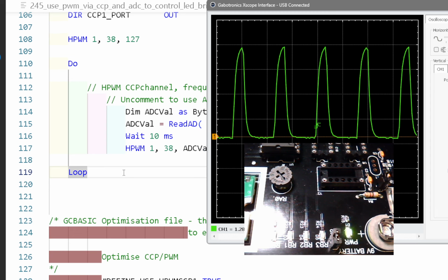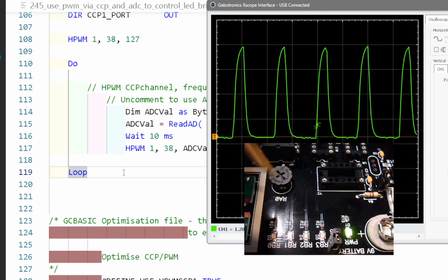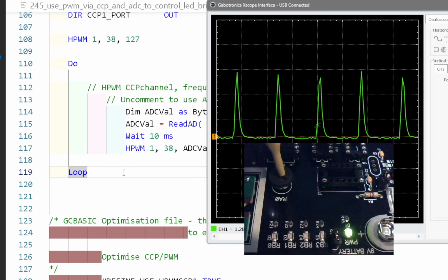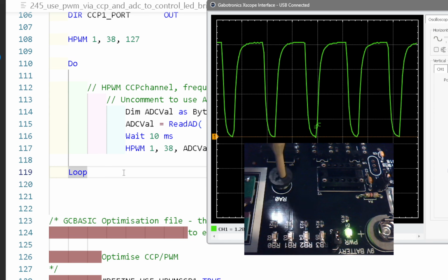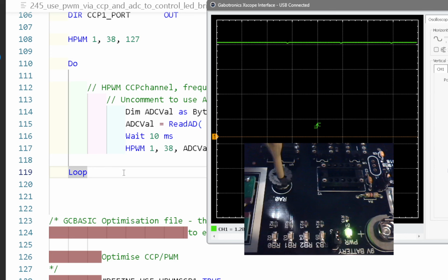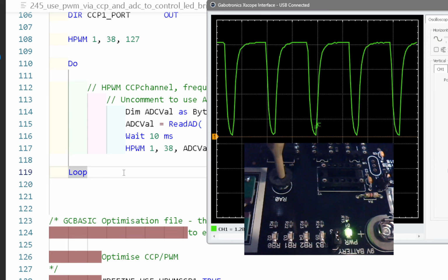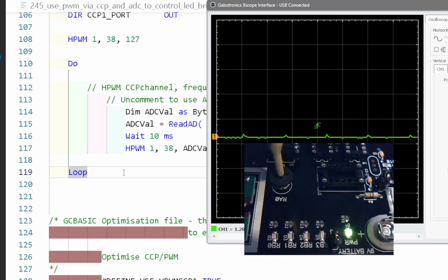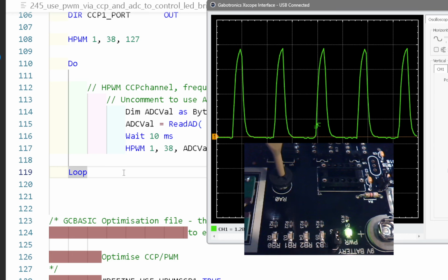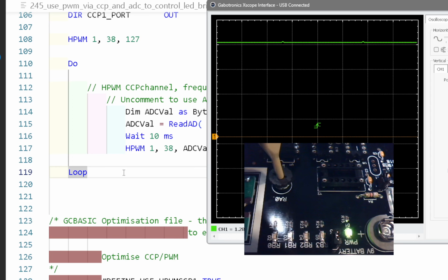there's no action on the second camera, but there will be, because I'm going to bring in my screwdriver. You can see the signal. You can see my hand coming on the LED. And as I rotate the potentiometer, that drops to 0 or to full. So now my potentiometer is controlling my duty. And you can also change the frequency on the fly. So this is variable mode, and all the grunt work, all the low-level assembly is all calculated for you. That's pretty good in reality.